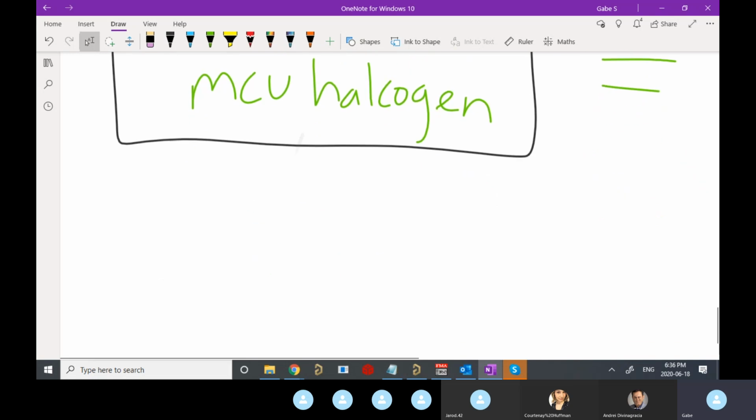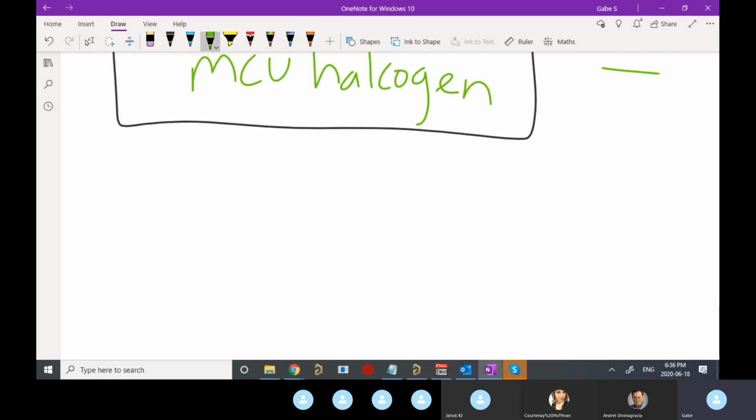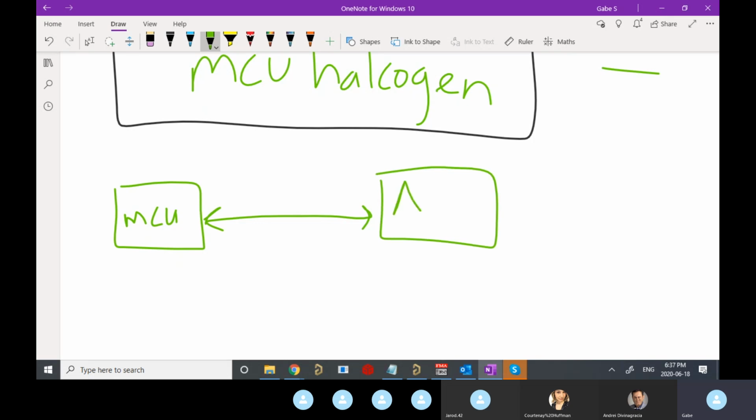If you're talking to something like a chip you bought off of DigiKey online somewhere, so let's say I'm talking to an ADC, and it's giving me data out over UART, it's usually going to have a fixed baud rate or fixed speed. You'll find that in the datasheet of the chip, right?